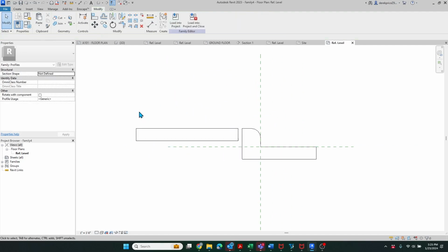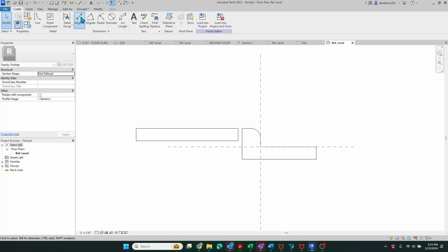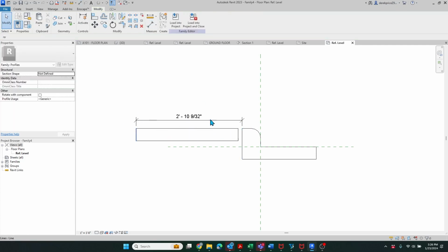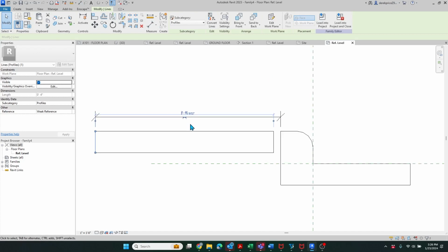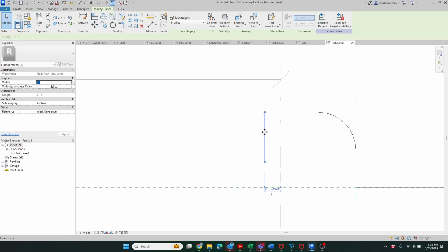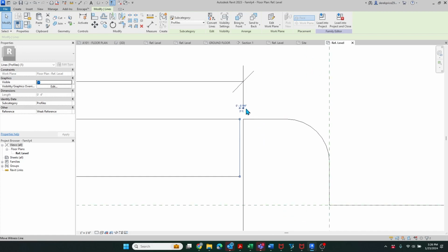And you could also put some constraints on here as far as how wide you want the sidewalk. But I think for this exercise, we're just going to do it pretty generic. So in our world, we're going to do a 5-foot sidewalk. And I just want to leave a little bit for a joint. 1/4 inch. Or maybe we'll go up to 1/2 inch.